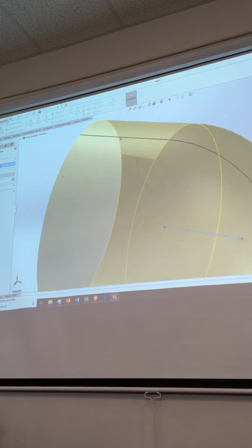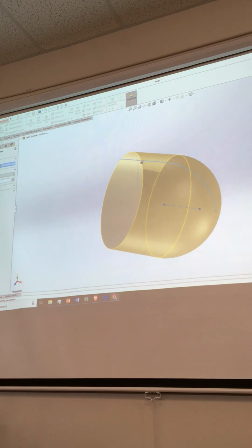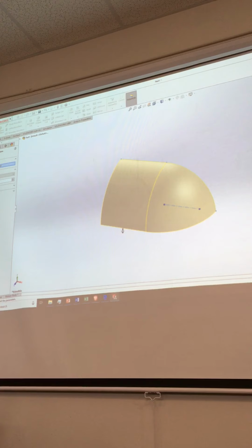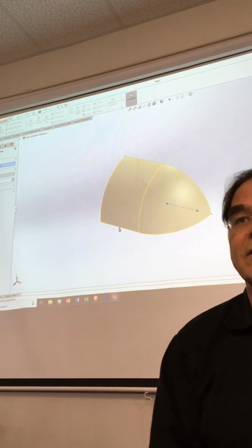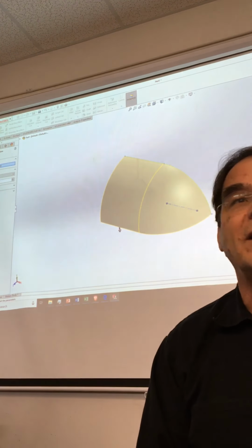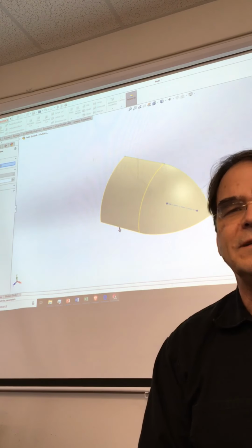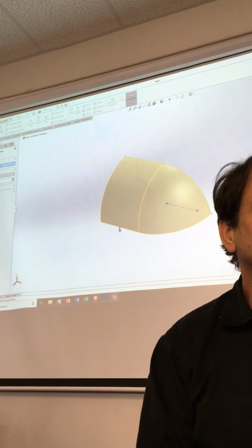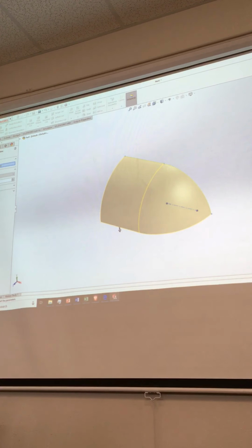Right, and it goes, oh, I want to revolve that, and I don't want 360 degrees. I'm going to only go for. So did you select a plane, or was yours already? No, it was. Because I got this weird message saying select a plane on which to sketch future cross section, or the existing sketch. Whenever you sketch, you need to have a plane selected first. So I had the front plane selected. Well, it didn't think you did for whatever reason, so go do it again. It's being rude, which is what it does.